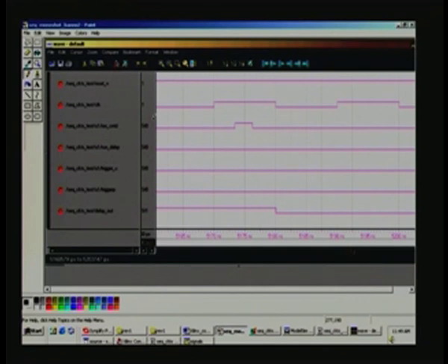So, if the timer had run precisely, it would have made 5100 exactly, but unfortunately we have some 3 nanoseconds extra here. So, that is the accuracy that you can have in this design, and this inaccuracy is created not by us or by our design, there is no design flaw as such, and the basic thing is the path delay has made all the difference.